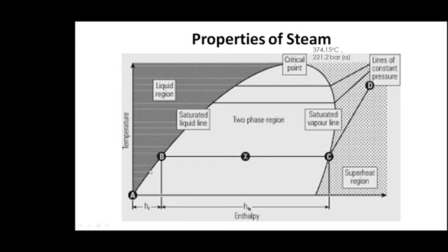Sensible heat will heat, but very, very slowly. Latent heat gives quick heat transfer, because there is going to be a phase change. When the steam condenses, it gives up a liberal amount of heat quickly. So one of the things we will see is energy conservation options. You use the steam at the lowest practicable pressure. Why? Because at the lowest pressure, we have very high latent heat.